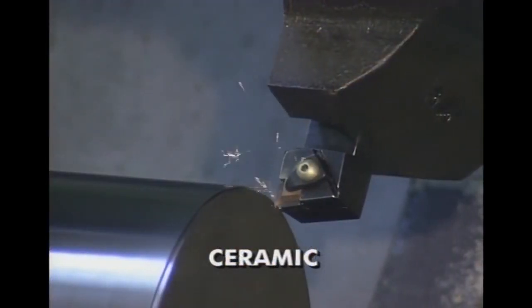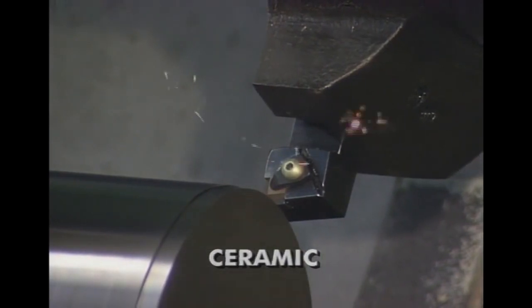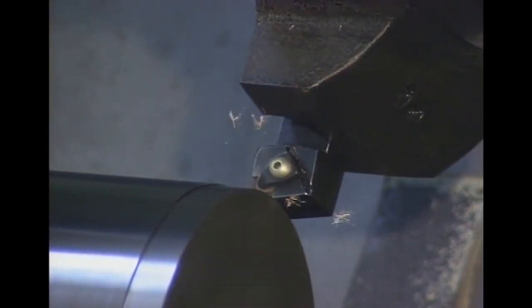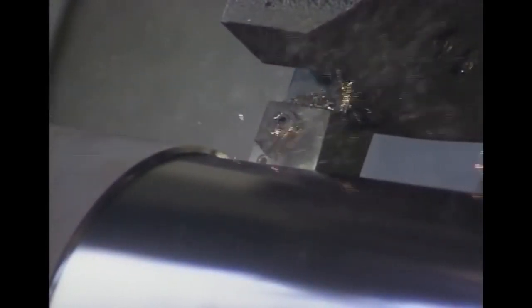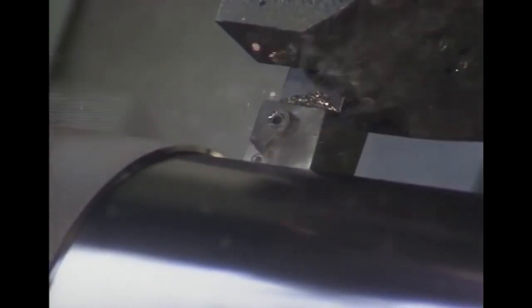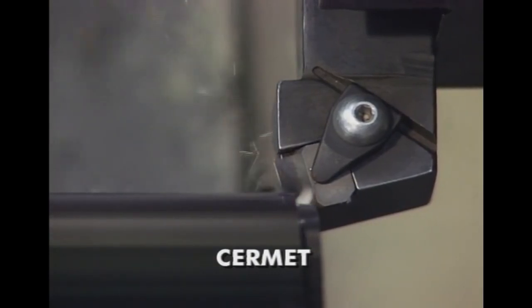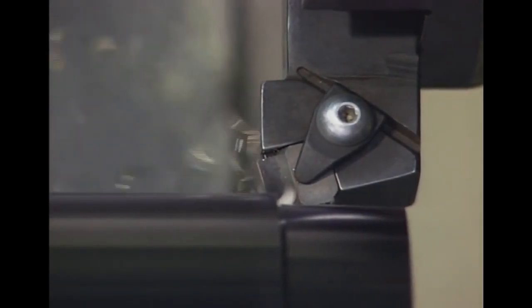Ceramic inserts may be alumina-based or silicon nitride-based. They withstand higher heat than carbide, have good resistance to abrasion, and they cut very fast. But ceramic inserts are less shock-resistant than carbide tools, so their applications are limited. Cermets are composed of titanium carbide or titanium nitride with excellent resistance to various forms of wear. But cermets do not withstand high heat well.